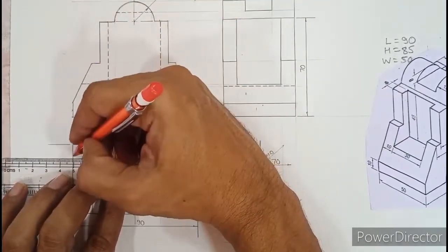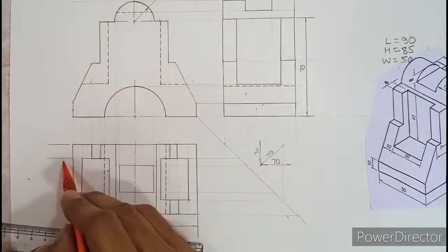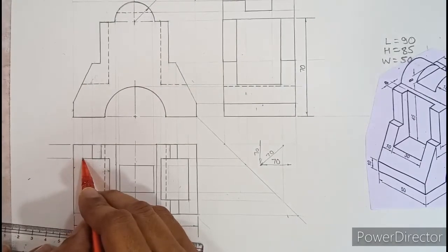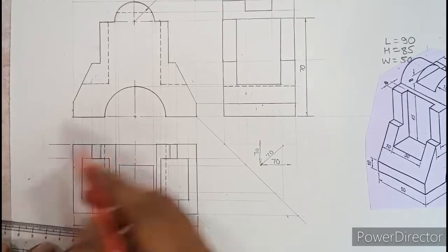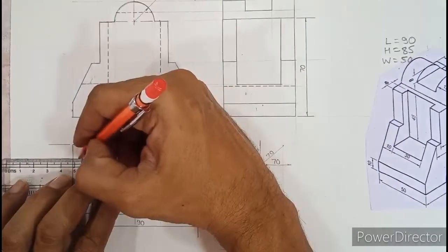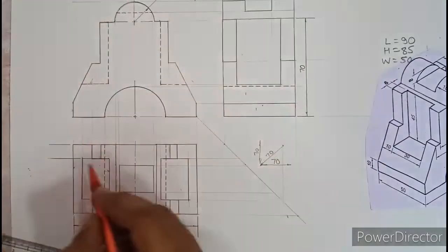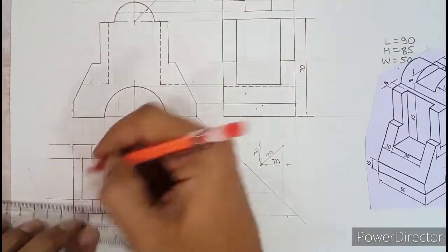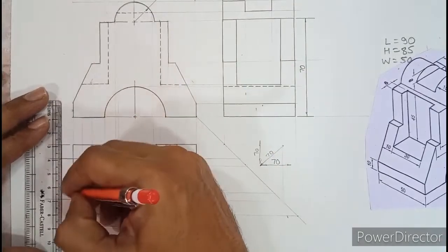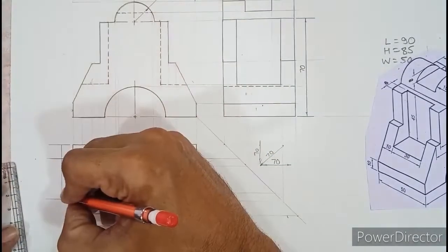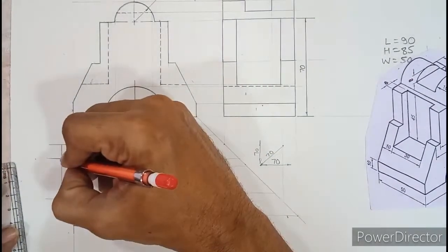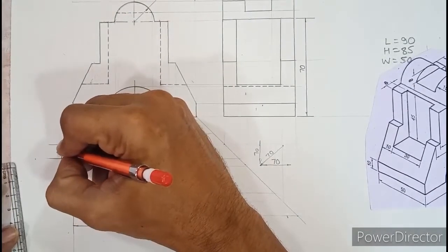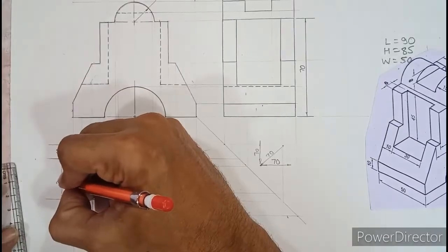Now 10, don't show from here, because if you show like this, it is not very clear where 10 is from and to. 10 actually is from here to here. But if you show the extension line from here, it is not clear. So what you do is, from here leave a 2 millimeter gap and then show the extension from inside. Similarly for 30, show the extension from inside and then a common line, and then you should write this as 10 as well as 30. Write 10 above the line and write 30 on this side.